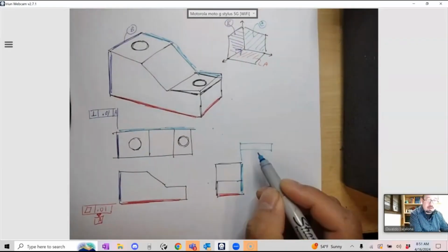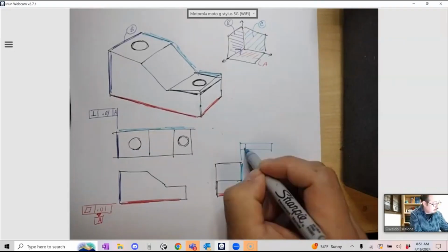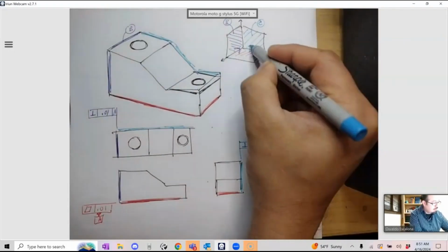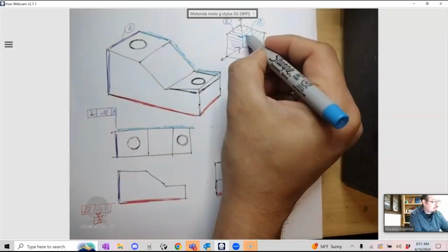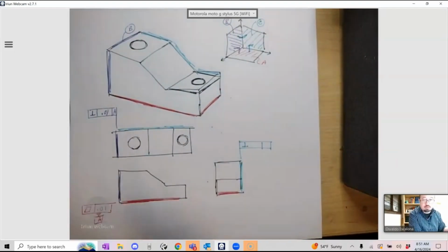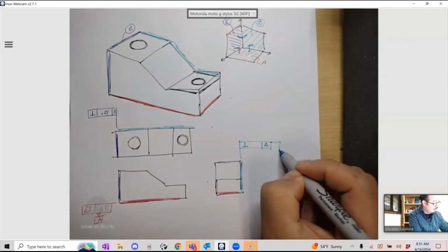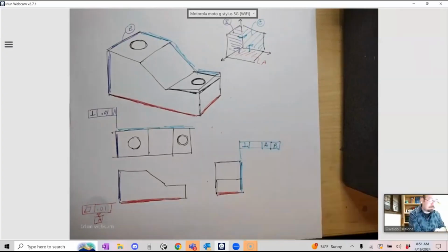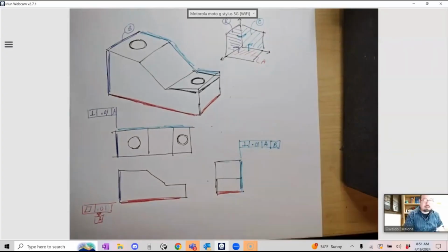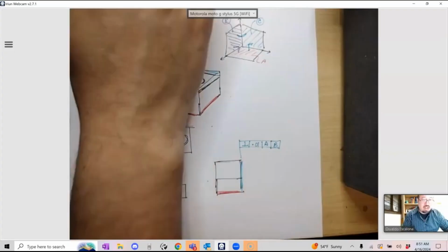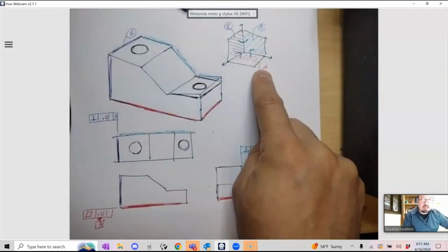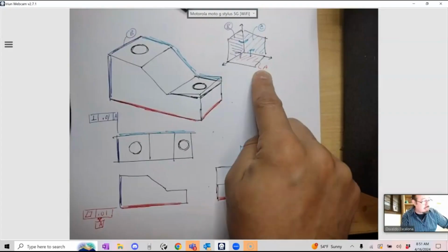I want to make sure this part is perpendicular to datum A, right? Perpendicular to datum A, and I also want to make it perpendicular to datum B, so I have something controlled to each other. So I want to say perpendicular to datum A and perpendicular to datum B, okay? And I want to make it perpendicular with 0.1. You guys see it? Okay, now I have mutual perpendicular planes, orthogonal perpendicular planes. I can grab my part, I can stick it in there.